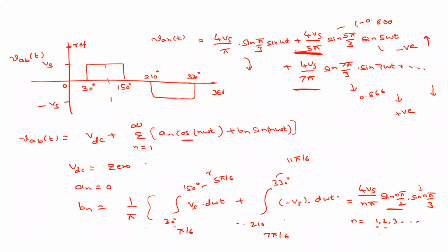So this you might have studied in electrical machines, particularly when you were studying the induction machine. In induction machines, we have some slots. The slots are angled by 30 degrees, right? You remember that. If those are angled by 30 degrees, all the triplet harmonics are eliminated. And the MMF shape will be like this. So this is the shape of the MMF in the air gap.